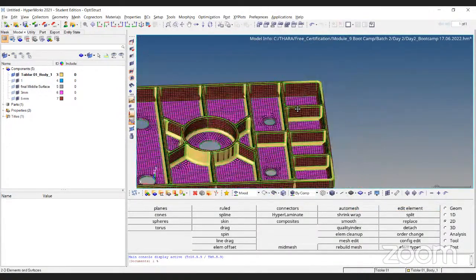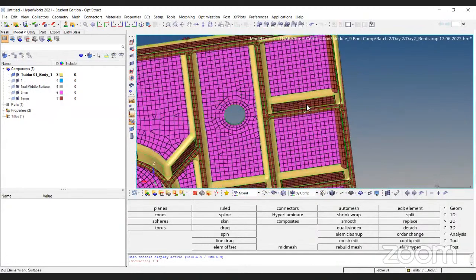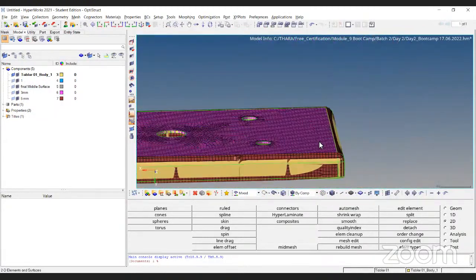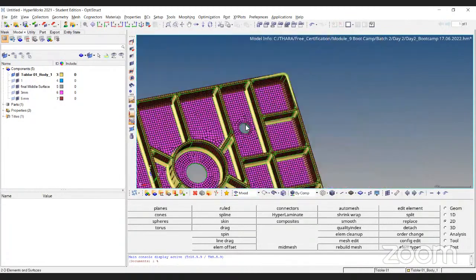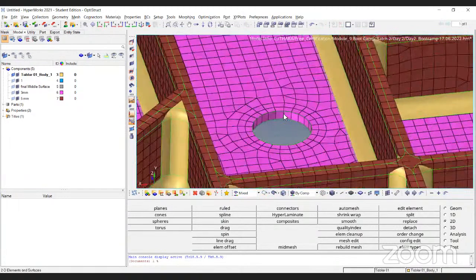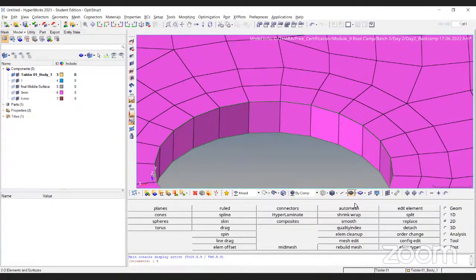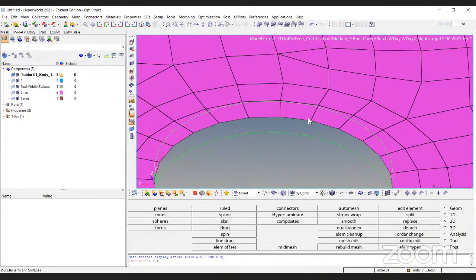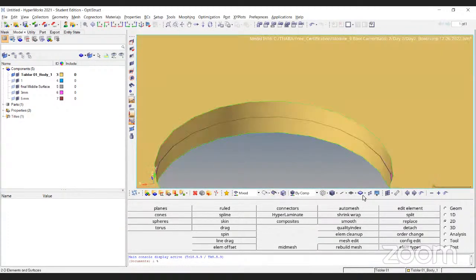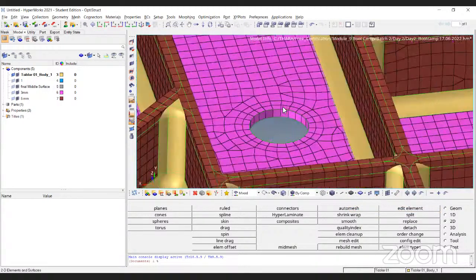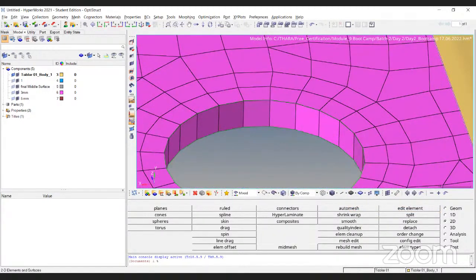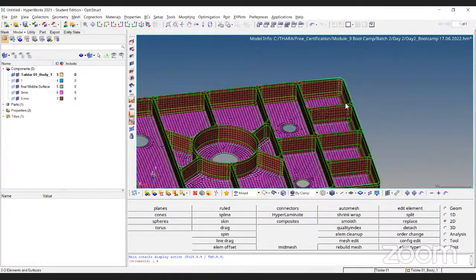Now see, even though I have meshed the single surface, you can now see the 3D representation of the element. That means I have assigned the thickness. Even though my elements are in the mid plane, after assigning the thickness, your component should look like this. It means it is matching with the CAD, and you have defined a correct thickness. So this is how we need to assign the thickness. We need to clear the quality and everything.